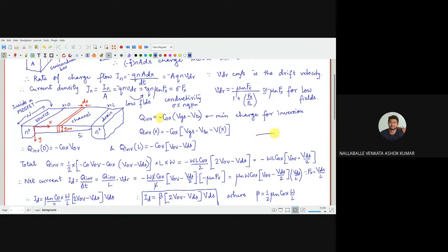So from the net charge equation, what is the voltage you are applying here? Positive or negative? Positive. Why? Because this is actually an N MOSFET, with N plus regions. So this is P silicon. This is actually P silicon here. This is N plus, N plus. This is like an isometric view. This is the cross-sectional view anyway.